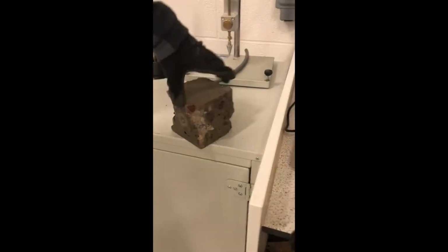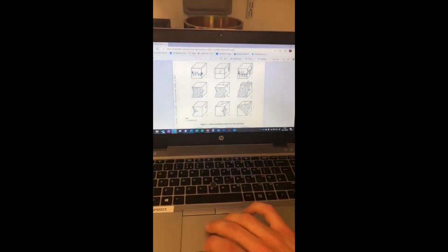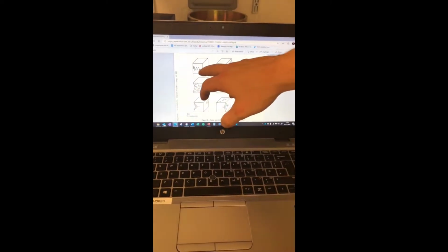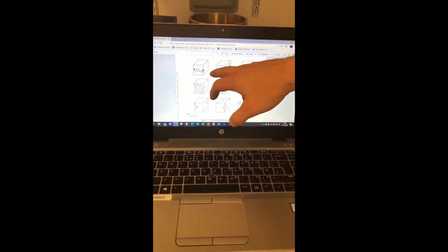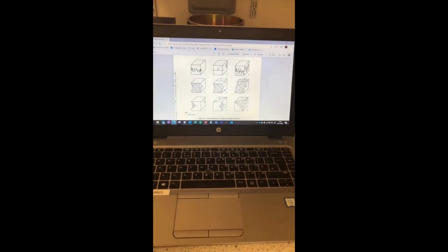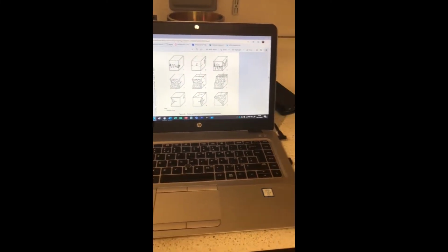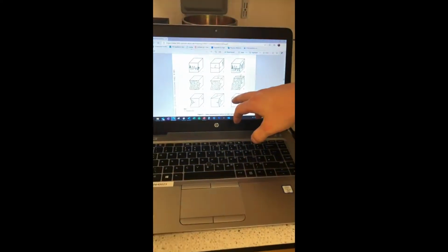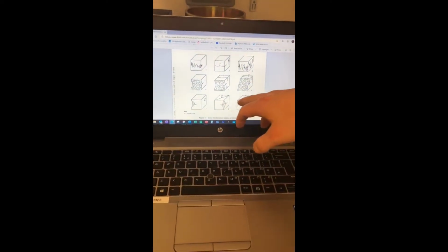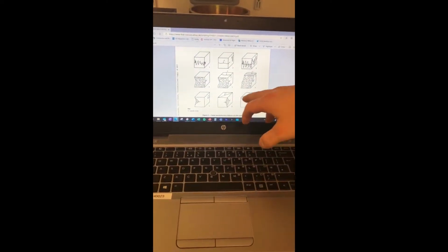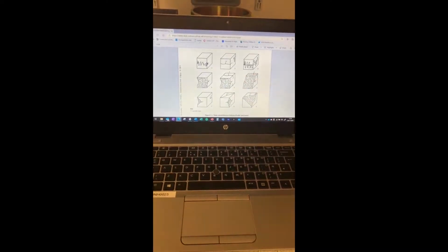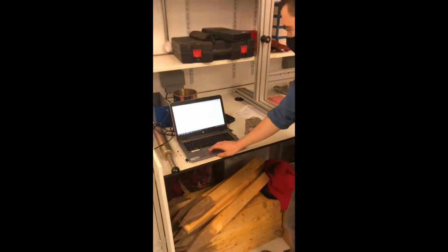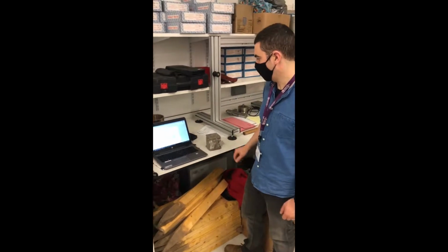You compare that to unsatisfactory failure types of cube specimens. Here we've got tensile cracking in various forms on the face of the cube. Our samples here don't have that. We've also got unsatisfactory failures where they've spalled away, like peeled away on one corner, one edge or one face. Ours is fairly uniform and consistent, so you'd say that would be a satisfactory failure.